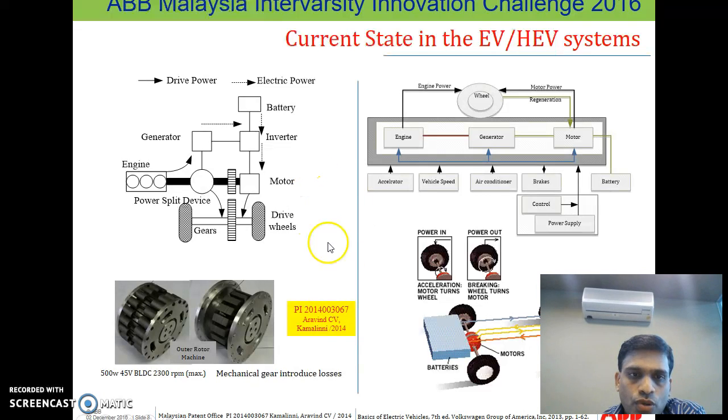So in this approach, what we want to do is have a magnetic gear attached to this mechanical system, so that when this is revolving at one point in time, your gear can rotate simultaneously depending upon the output characteristics. Say, for example, if you have a magnet here, I put another magnet here. If this magnet is rotated because of the electric vehicle, your external will be connected to the actual wheel. So when this rotates in one direction, your external will be rotating 3 times if you are using 1:3, so that your rotation will be faster or the gear will be more.